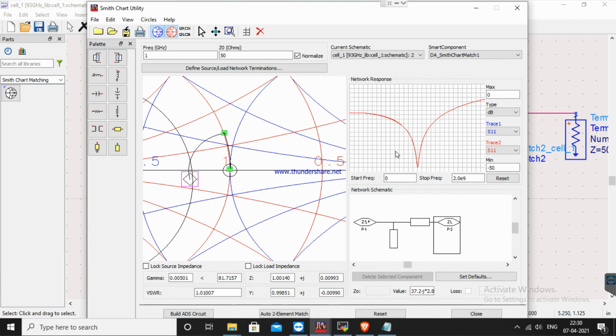And here you can see the matching, whether I'm able to do the matching or not. If you compare with the last solution in our Smith chart, our open stub was around 16.56 and we are getting 16.38 here in degrees, close by, and our microstrip line was 48.24 and we are getting around 48. So correct, we are getting it correctly.